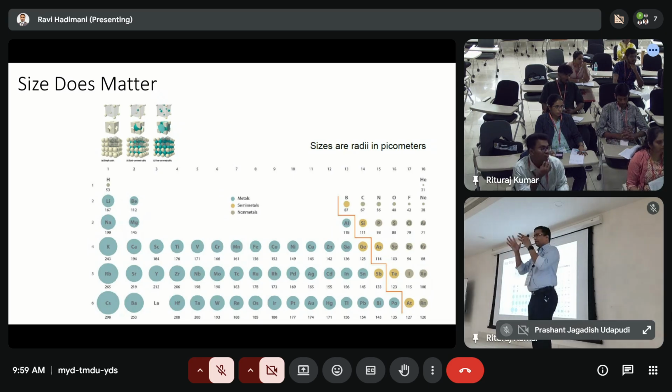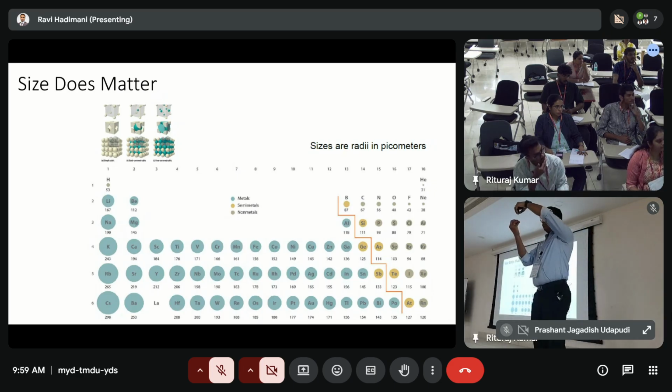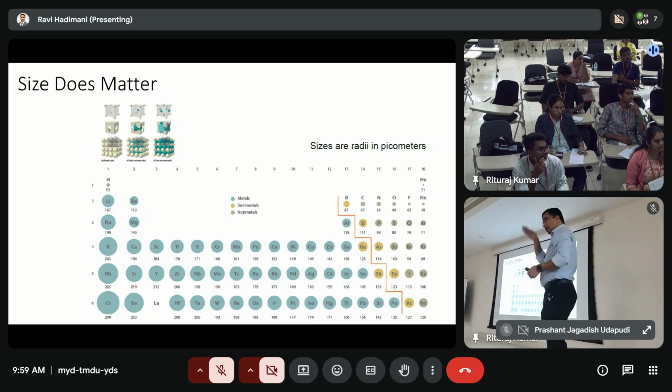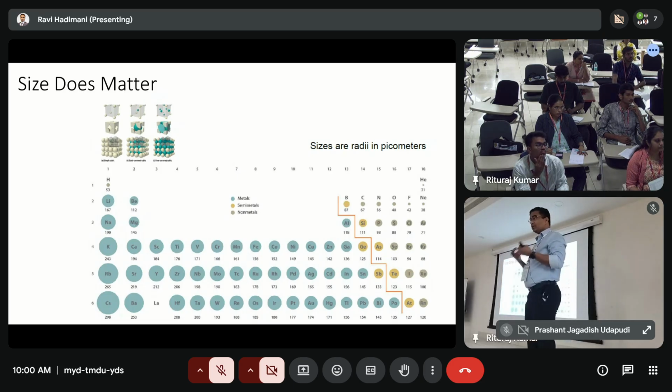But if one is really big and one is small, and then you have more atoms, what you are basically doing is creating some residual stresses between the top layer and the substrate. If they have similar atomic radii, then there won't be internal stresses in the thin film.